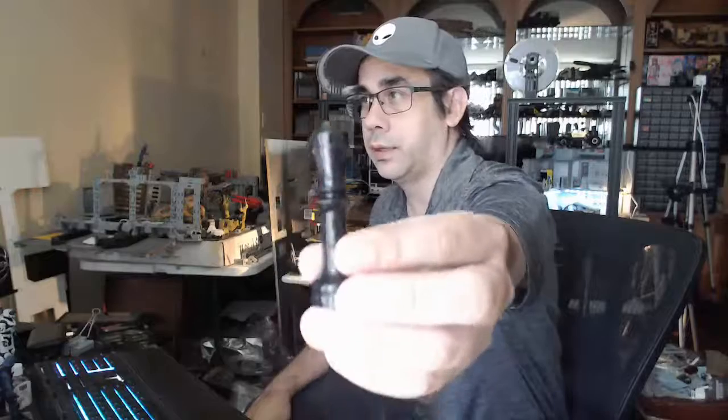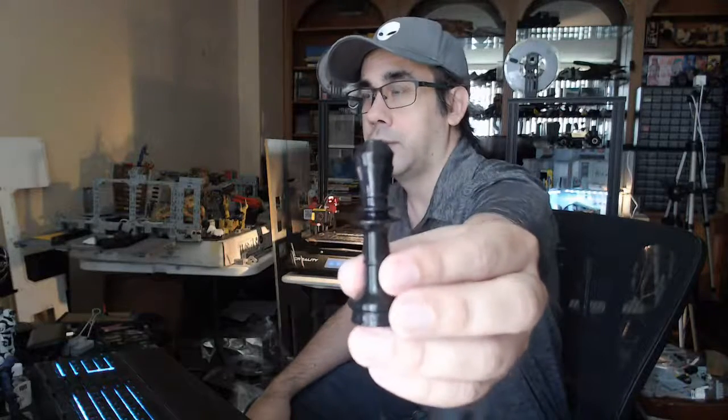So here's a part that is glossy smooth. This was printed with a regular FDM printer, but with the plastics we use, we can suppress the layer lines, so you get this glossy finished touch. And this is really friendly for painting. A lot of our hero parts, the parts that are going to be in front of the camera if you do toy photography, get this type of treatment. A lot of the other background stuff that's not hero parts, like larger props, we don't do this treatment with.